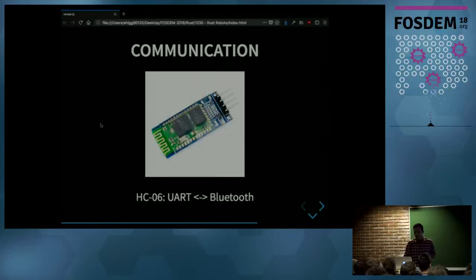And the communication module is one module where Rust really shined. I'm using this module for communicating wirelessly between the robots and my laptop or my phone. This module accepts a serial interface from the microcontroller, which is a simplified interface, so the microcontroller doesn't have to implement the Bluetooth stack. I use this mainly to log data from the robot so I can analyze it later on.